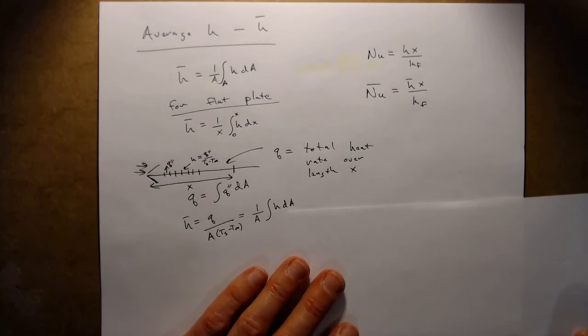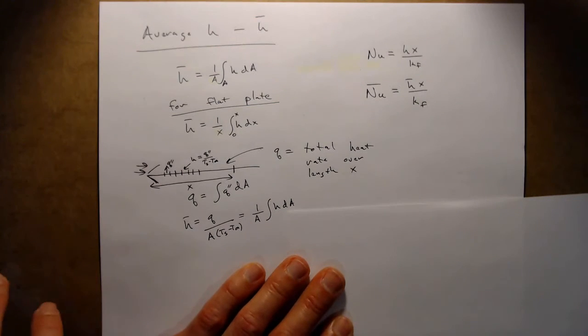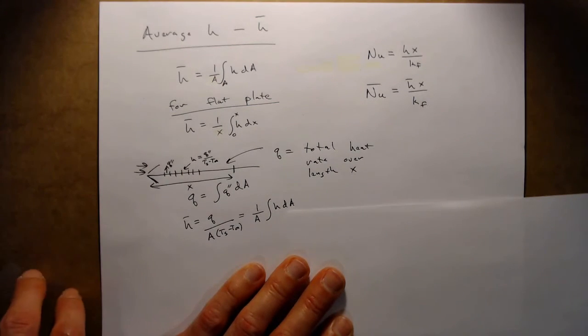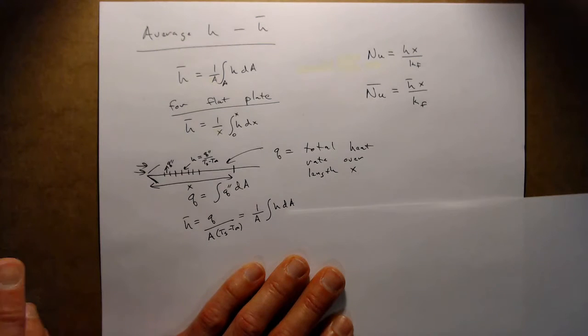Now, importantly, that was the local heat transfer coefficient. So we were able to answer what is the heat flux at a specific point. On the other hand, if I'd ask you how much heat was the plate losing over that entire length, what was the heat rate, how many watts were being dissipated by that entire plate, then you would need to evaluate that heat transfer at all points in the plate and add them up, integrate that heat flux over the plate.